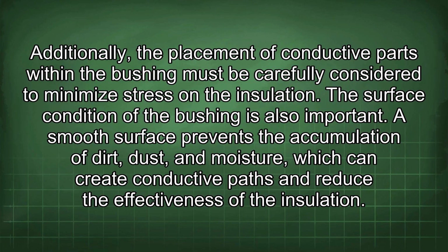The surface condition of the bushing is also important. A smooth surface prevents the accumulation of dirt, dust, and moisture, which can create conductive paths and reduce the effectiveness of the insulation.